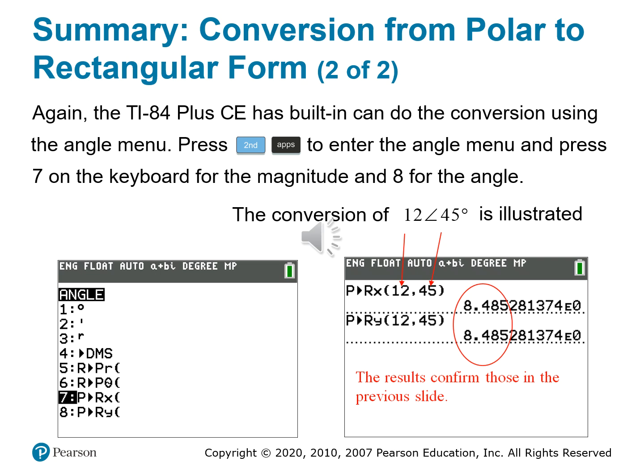Well, here's where things connect. Remember how we dealt with phasors in the RL circuits. You might have been handed a voltage or a current in polar form, especially when using impedance analysis. But to analyze voltages in parallel branches or to solve for time domain response, you need to add those vectors in rectangular form. So you can see a reason to be changing from polar to rectangular or rectangular to polar.